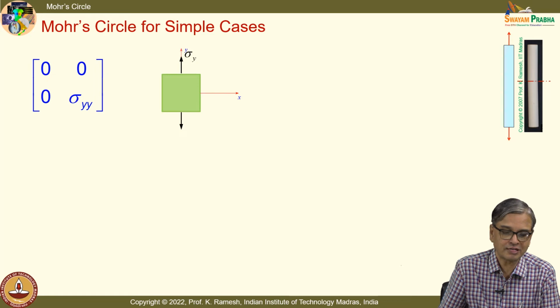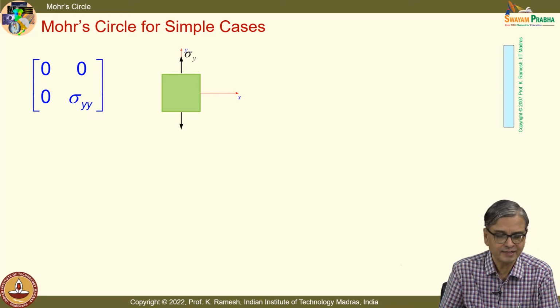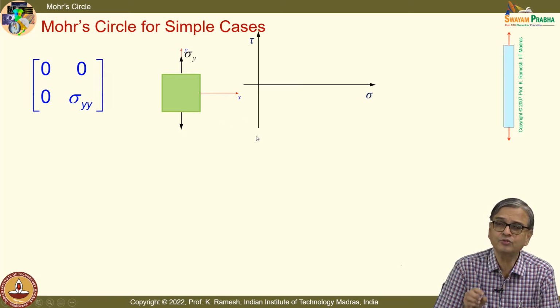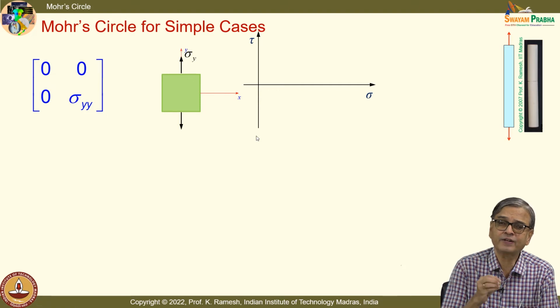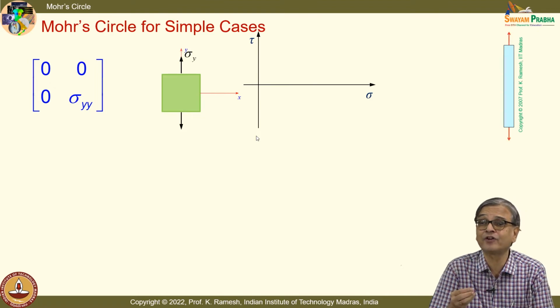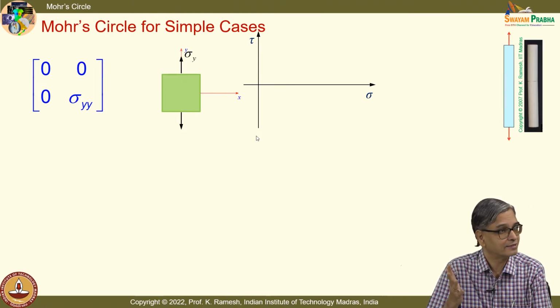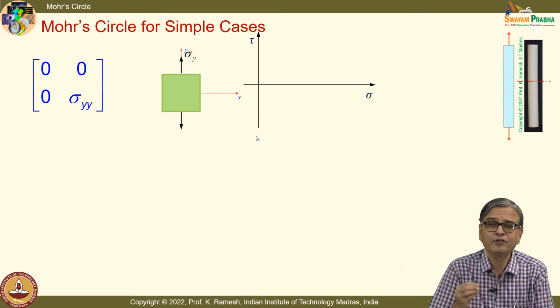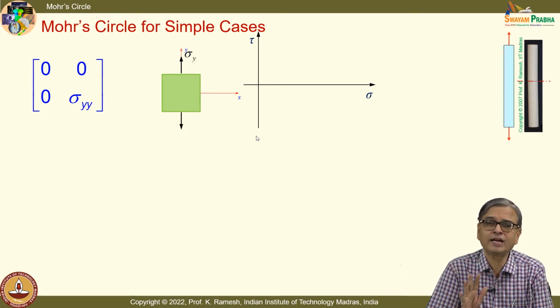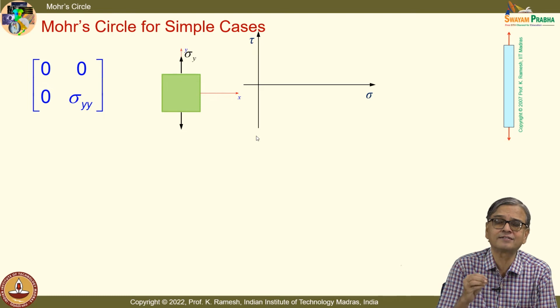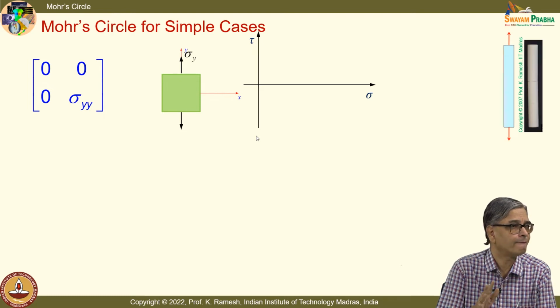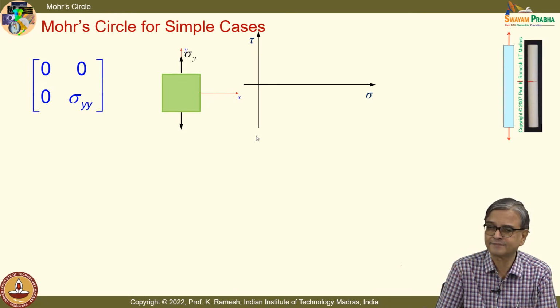You can draw the Mohr circle, which you have already done. And for us to find out whether the chalk will break or not, I should know what is the failure criteria for a brittle material. Fine. For the current discussion, when the normal stress reaches a critical value, failure would occur.